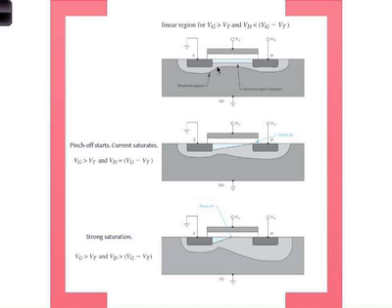But you also have this gray region, which is the depletion region. As you increase the drain voltage, this junction becomes more and more reverse biased, so the depletion region will get bigger and bigger and will encroach into the inversion region as shown here, and that's what causes pinch-off and saturation. It's a little bit different mechanism than the FET, where it was just the depletion region cutting off the channel, right?